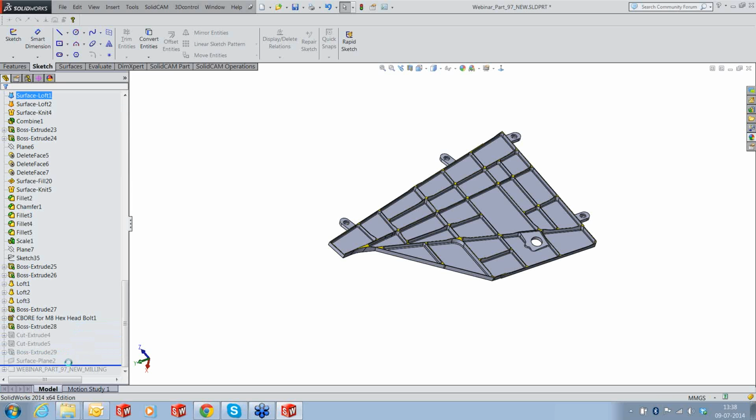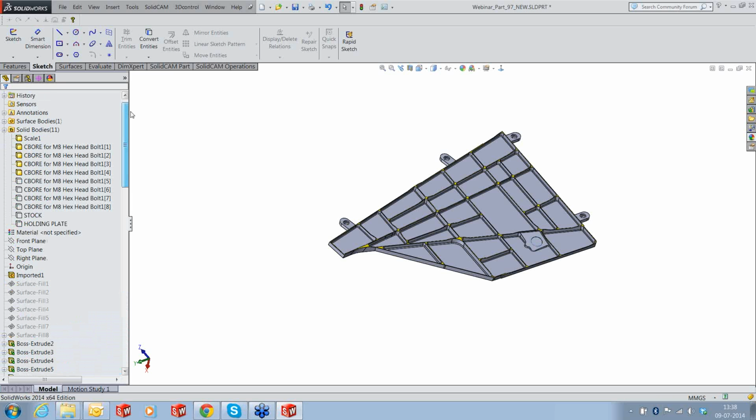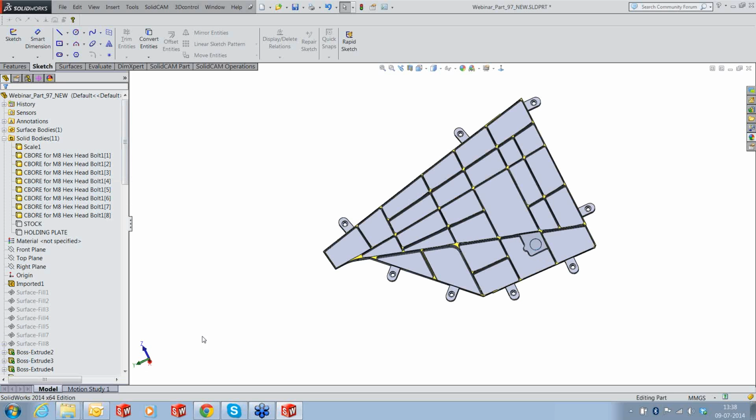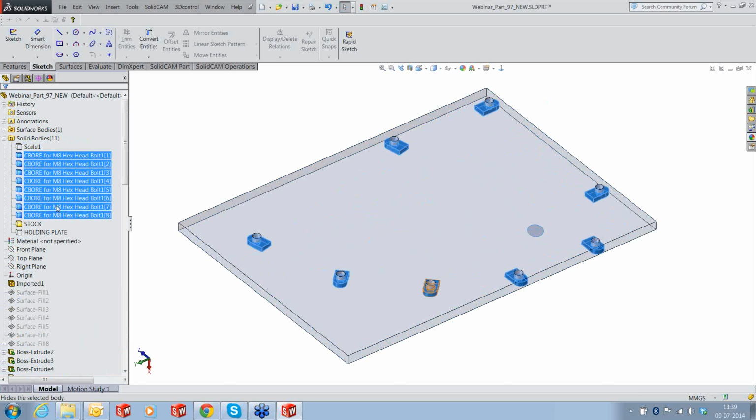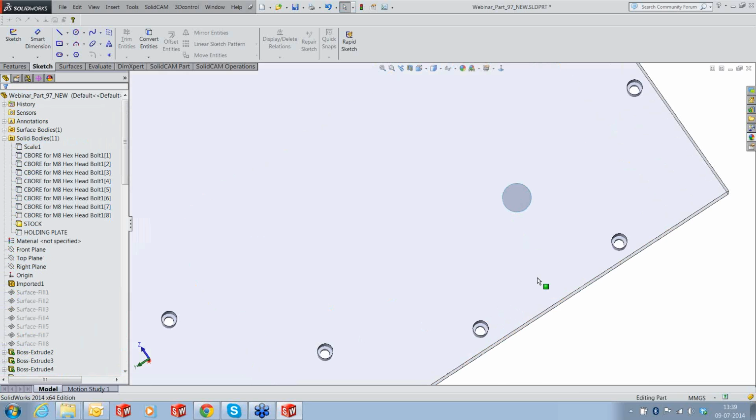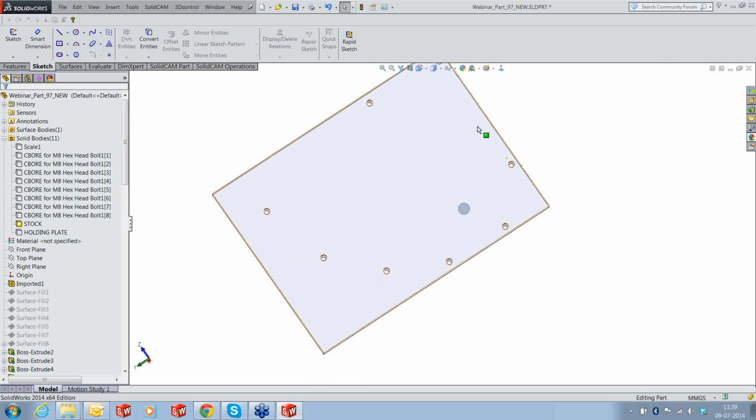Another one, and if I switch on, then this is how the entire lug. Define the stock. We define the stock as a part of this particular stock. Now, if I switch on the CAD data and all of the lugs, you will see that the stock also has a counter bore. So I'm going to put an M8 screw in all of these holes and tighten this plate down onto the